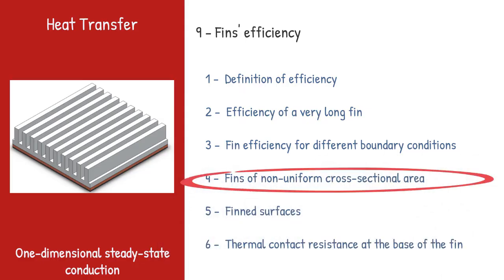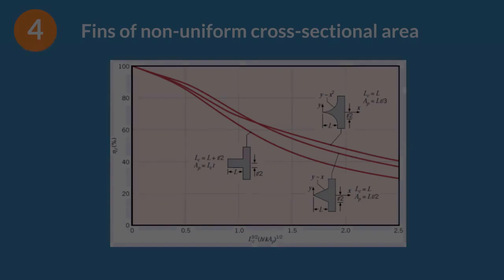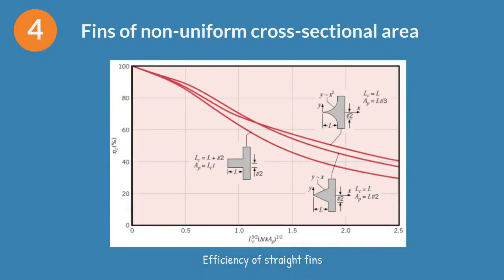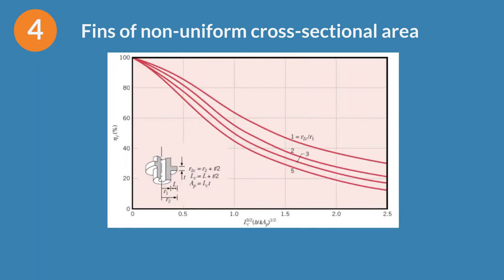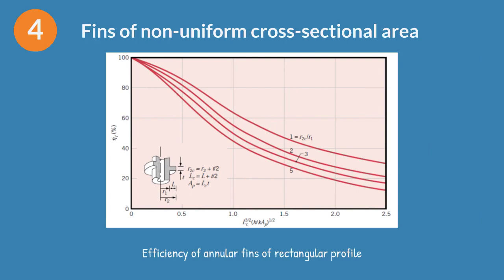What about fins of non-uniform cross-sectional area? There are many fins of non-uniform cross-sectional area. In that case, you must look for the efficiency of the fins in tables or graphs.